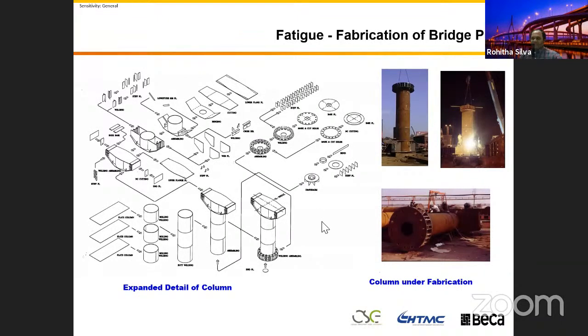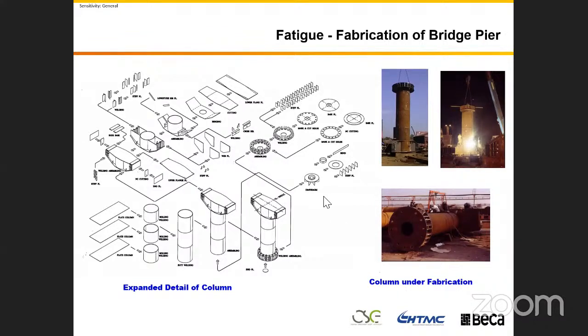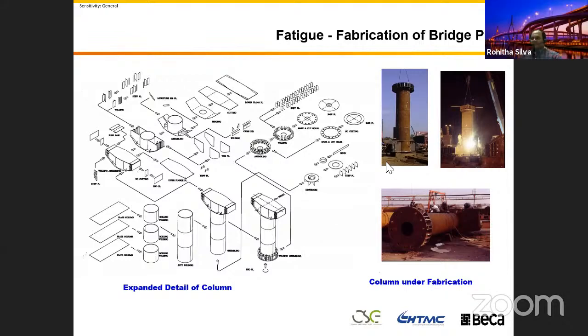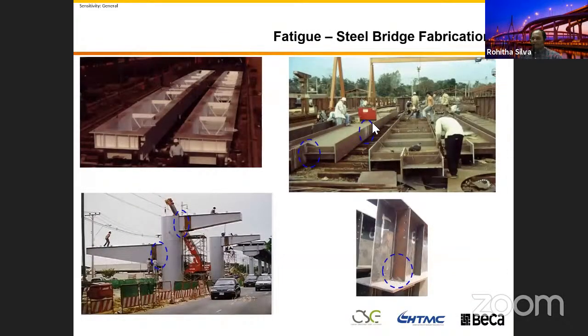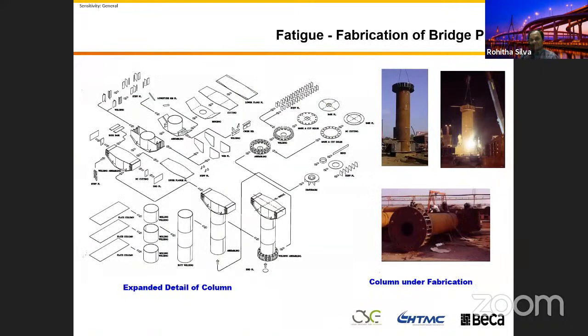But to answer your question, as far as I know, there is no special consideration given for curvature. Of course, we do have curvatures in bridges. For example, this 25-meter-long steel bridge, we fabricate with a 45-millimeter camber built into it. During construction it is going to go flat, but in terms of fatigue design, no, we don't, as far as I can remember.